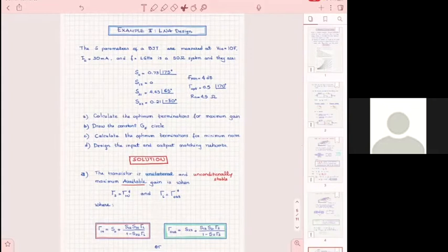So you said Z naught equals square root of L over C. Then what about if there are more stages? Then there are more L's and C's. Then you follow the same thing. You will always use the same law and the same high impedance, but the lengths will be different.